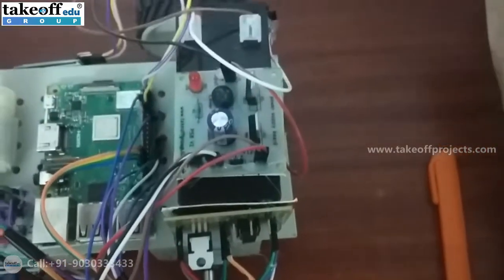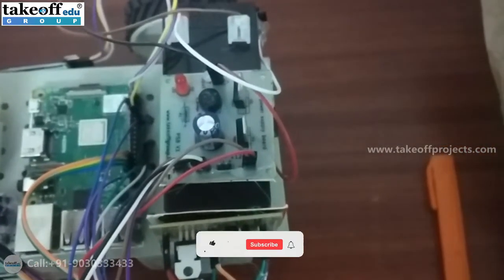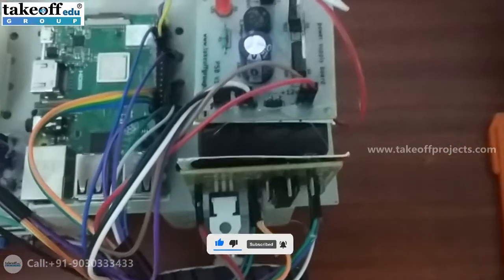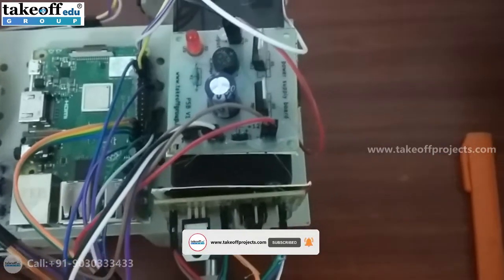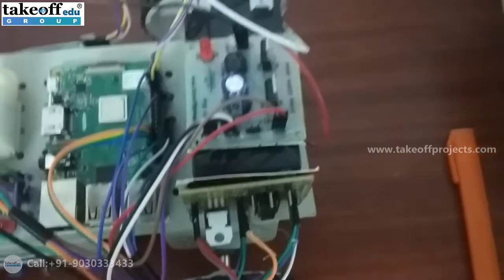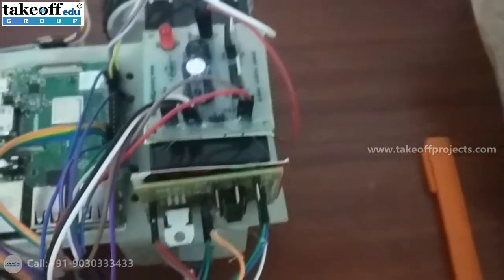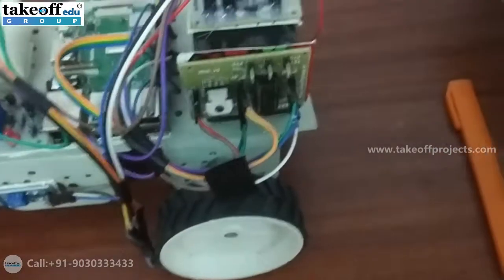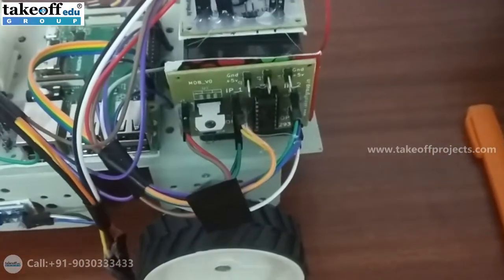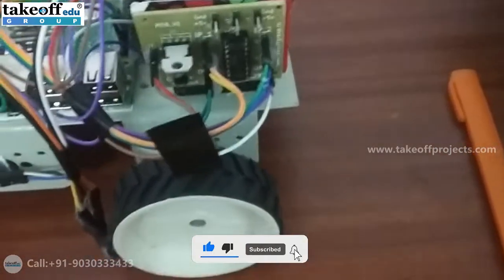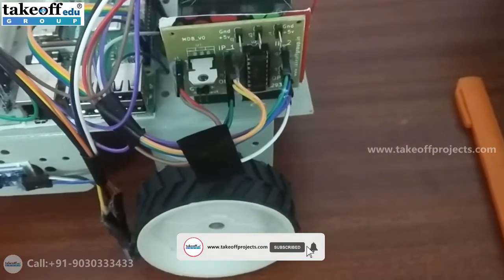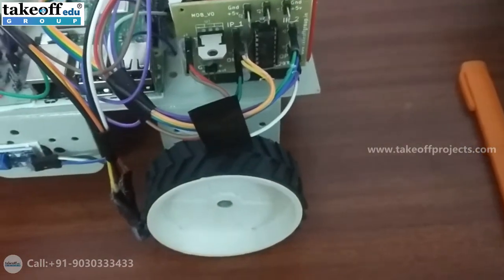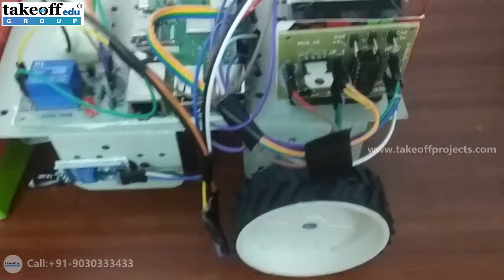And this is a power supply board, whereas from battery we are getting 12 volts of input voltage, which also contains some amount of presence of AC voltage in it. Using this power supply board we will rectify that AC and filter that to a pure DC, and will regulate the output to 12 volts and 5 volts pure DC. And this 12 volts is given to the motor driver module input, whereas this motor driver module will be used to control the direction of the robotic vehicle.